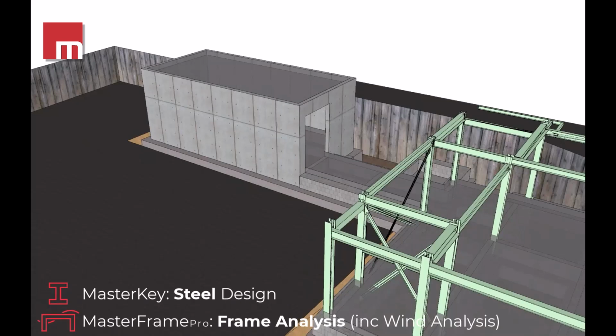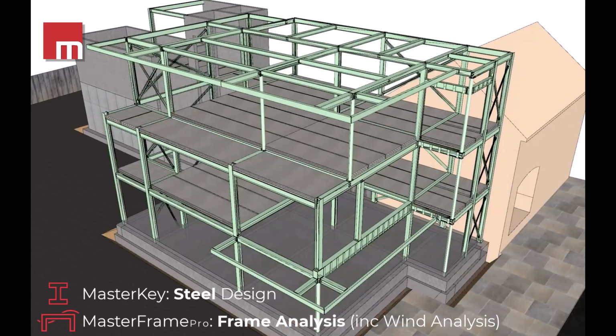So we can talk a bit about the steel frame and the selection of steel as the material of choice here. From a structural perspective, the main frame could have been designed as a steel, concrete, or even a timber frame, as the spans were fairly modest, around 6 or 7 meters maximum spacing between columns. But for this site, the foundations were critical, and keeping the loads on the foundation line was a priority, so concrete was less favoured. And structurally, timber could have been chosen for the frame, but there were some specifications within the client brief which ruled out timber as a suitable construction type fairly early on. So steel was chosen for the frame.